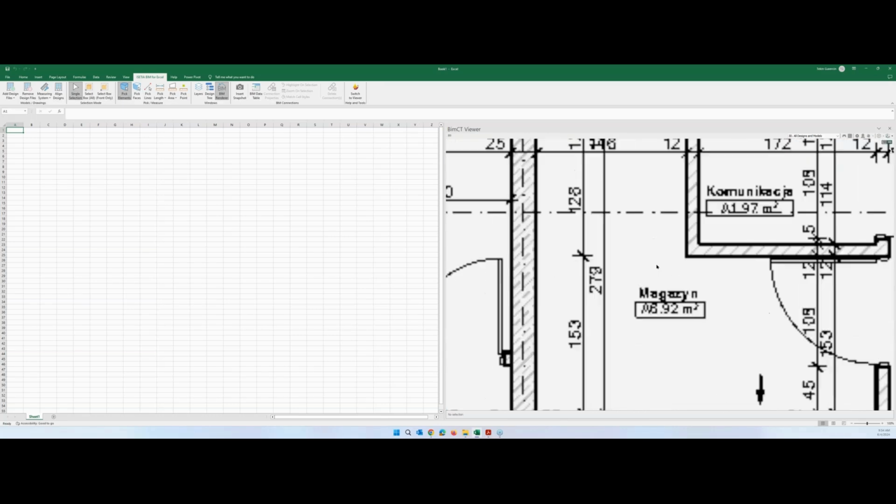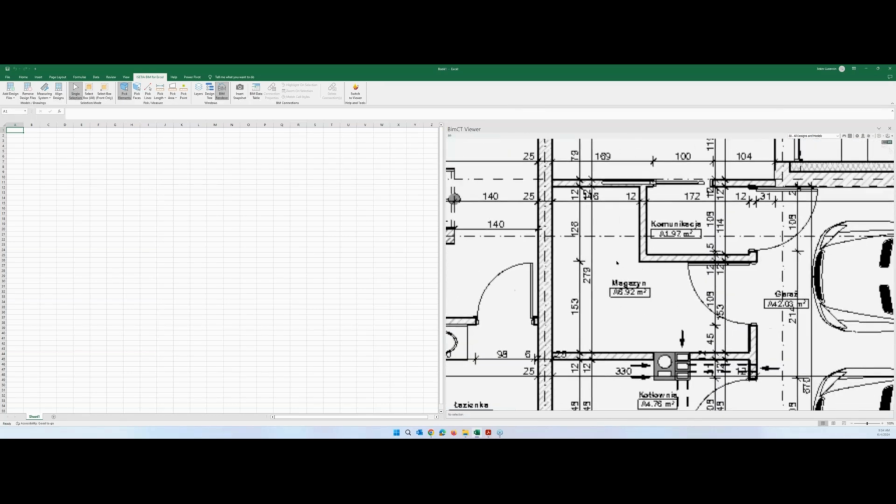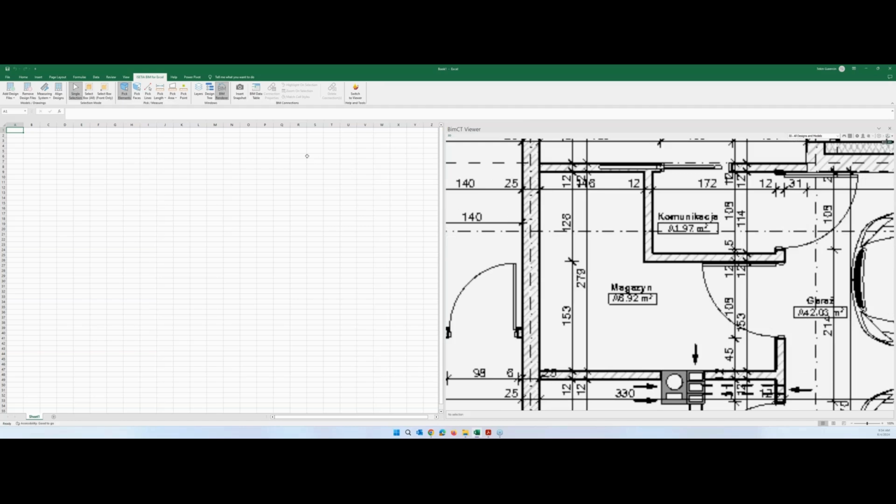Okay, you can see that we can zoom in and zoom out. And even in the PDF, we can estimate it, for example, with the estimation functions, because I would like to calculate the area. Select the area. And you are able to, for example, define the walls. Okay, so you just have it here, enter. System calculated here 679.